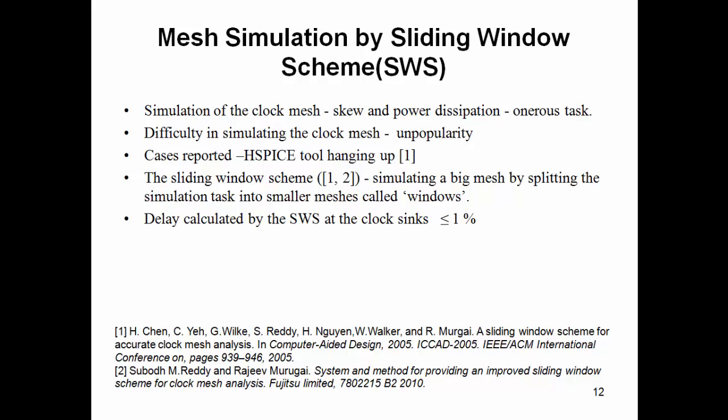Now when we consider simulating a clock mesh, we have to simulate the clock mesh to know the skew and the power dissipation. This is a very difficult, very time consuming task. In fact, the difficulty in simulating the clock mesh was the reason for its unpopularity till recent years. And there had been cases of HSpice, which is a very efficient tool from Synopsys, even hanging up when they tried to simulate a clock mesh.